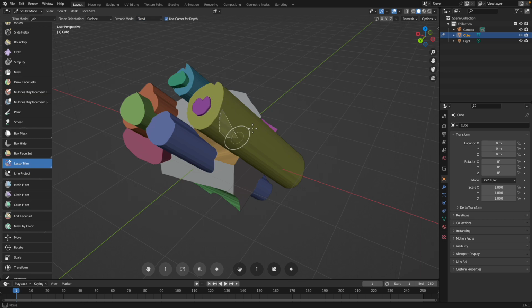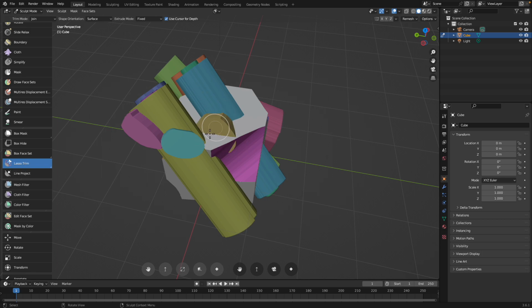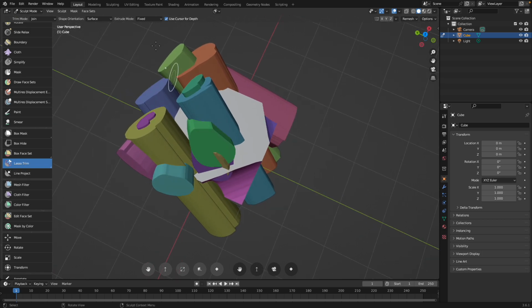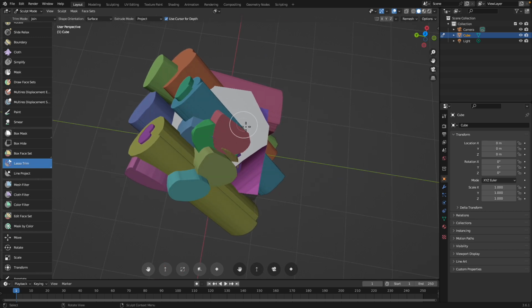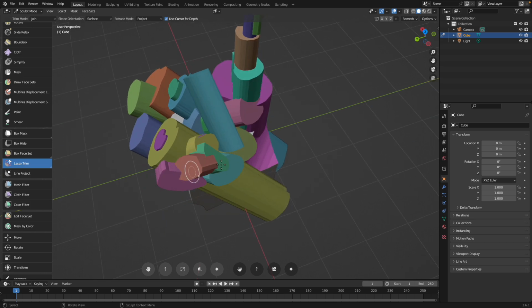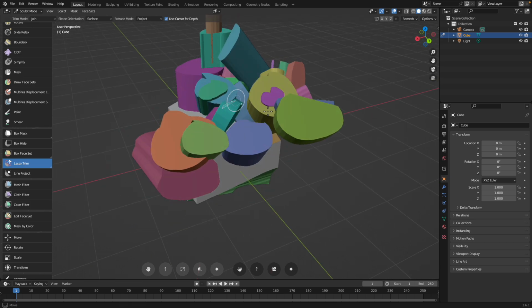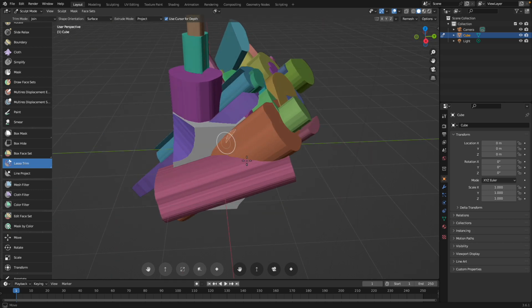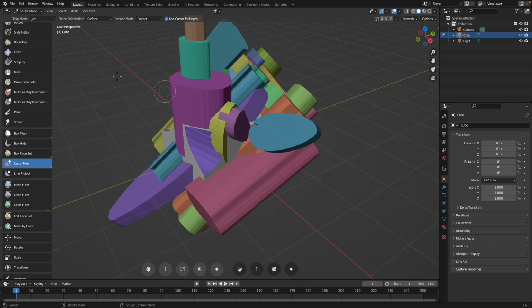And this is pretty cool. I like this a lot. You can just press F, and then the extrusion will be longer, and then F again to make it smaller, so the extrusion now will be less. But this is also super fun already. It comes with Blender, so this feature is already built in for sculpt mode.